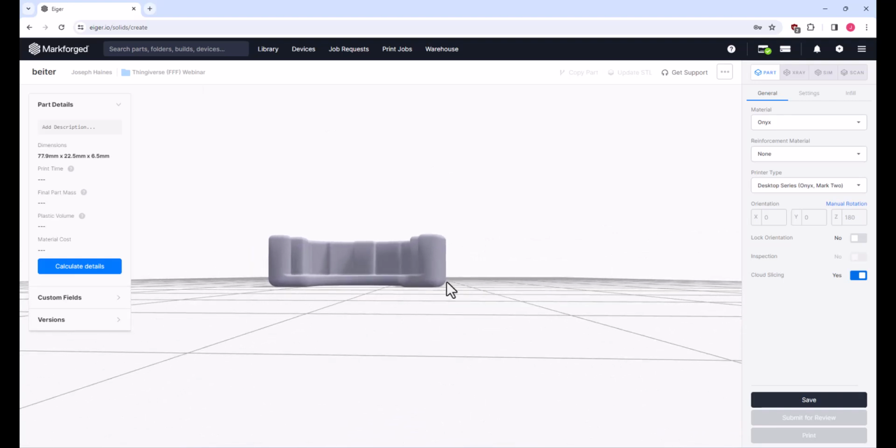When you're going to design parts with the intention of 3D printing, it's always better to route chamfers instead of fillets on these surfaces. Say you really need a fillet in this area, you can do what's called a faux fillet, where you put a chamfer in to start with, and then you fillet off the rest as you transition from the chamfer to that vertical face.